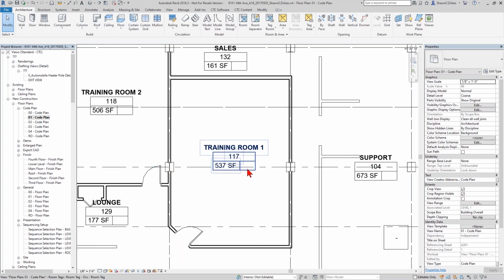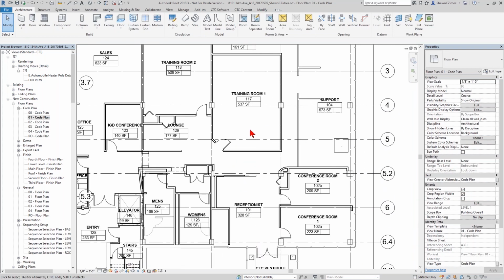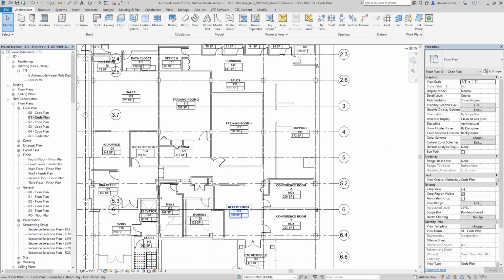But I'm not doing occupancy just for the sake of doing occupancy. I want to then leverage that to figure out, based on code compliancy calcs, how many water closets, lavs, drinking fountains, urinals, whatever, do I need on this floor or in a certain smoke compartment, or, you name it. How do you want to calculate that out? We need to find a way to do that, and it's beyond just occupancy.